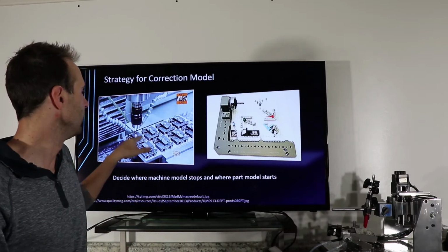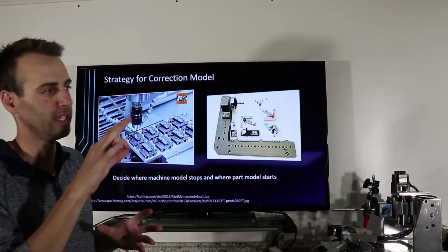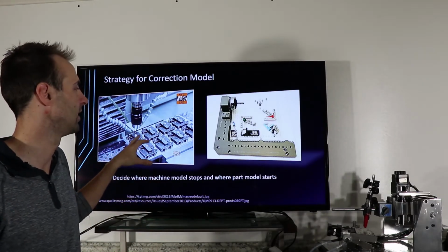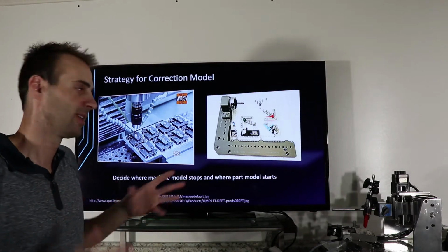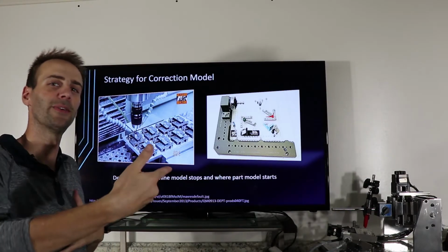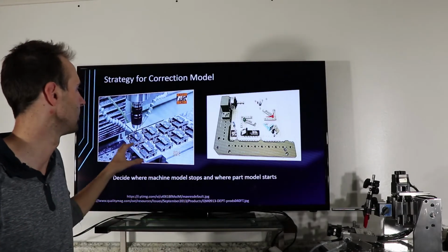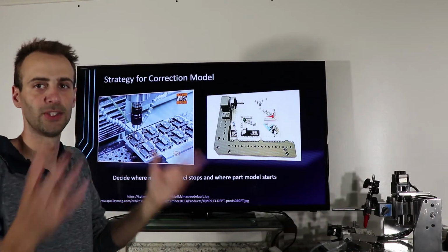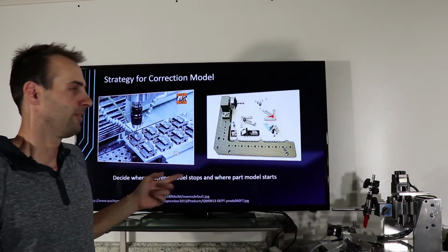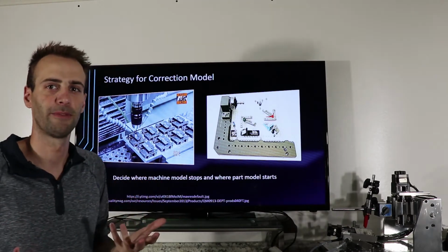You're going to do this through all the offsets and errors because it's a CNC machine. So normally you come in with your wiggler or whatever and index a hole, or some feature on this fixture plate. It's the same concept as your work offsets, but you're doing them, remember, in the code that we're going to write that intercepts the G code prior to it ever getting to those work offsets. Once again, just like your tool selection, this needs to be thought of up front.